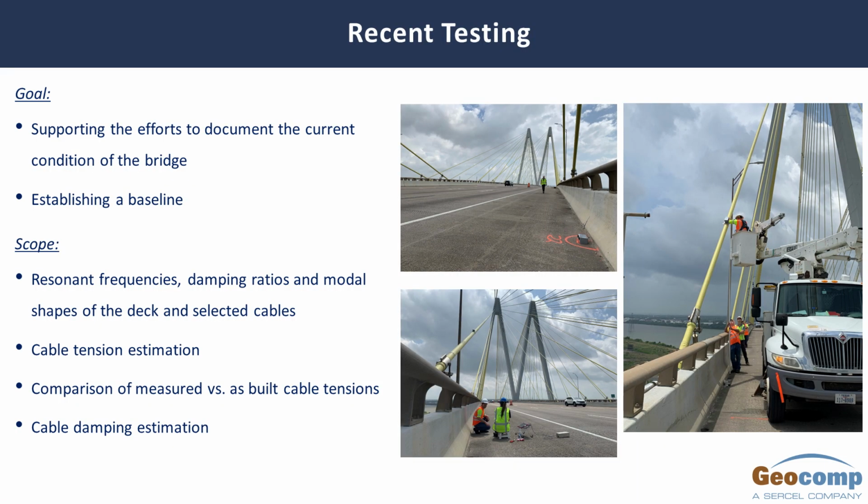At the end of this presentation, you are going to see that we will talk about coupled deck plus cable behavior, coupled behavior, which is going to be a good representation of what I just mentioned. The scope of this project was, by using our wireless distributed vibration sensors, extracting the resonant frequencies of the structure, damping ratios of the structure, and the corresponding mode shapes.